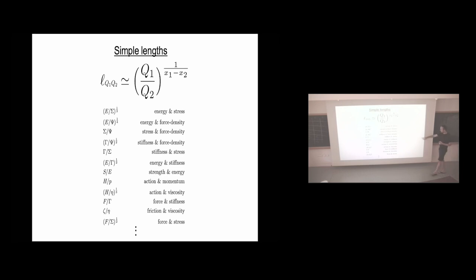So we know this one. This one is surface tension and elastic modulus, for instance. It is called the elastocapillary length. It shows up in a bunch of different contexts, but one instance is when you have a drop on an elastic substrate. If it's on a completely rigid substrate, the drop is going to have some shape depending on the wettability. But if you have a soft substrate, the substrate is also going to deform. And so you're going to have a ridge, and the characteristic length of this ridge is going to be given by this ratio.